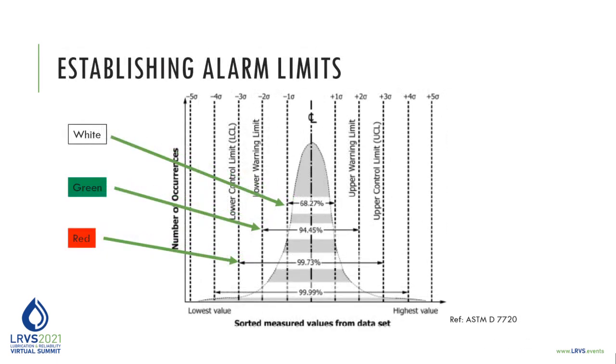For a large number of assets, or fleets, you want to select data from at least 10 different consecutive samples for each machine in that equipment population. The more consecutive samples would be expected to improve the initial quality of the alarm limits being set. And a higher number should be considered when the alarm limits are applied to, say, critical equipment rather than non-critical equipment. You don't want to selectively pick through the data or randomly pick samples from the data for this data set. Selectively picked sample data, all those values can introduce some bias for sure. Randomly picked data from a measuring data set for a large fleet, that doesn't always reflect the failure modes either.